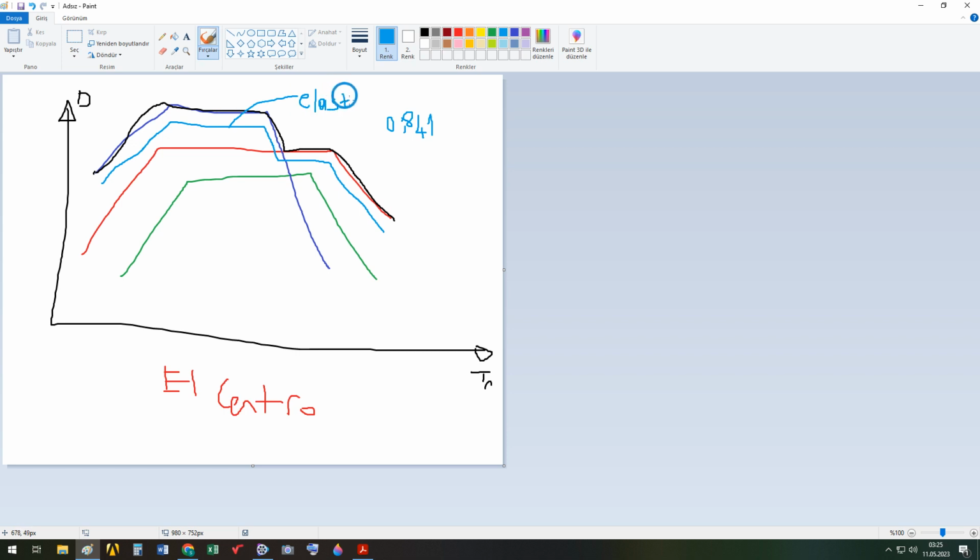Not very expensive. This is elastic design spectrum, which is created from the response spectrums of the earthquakes developed at the same place. Not 100% safe, but with 84.1% probability it is safe. But there is approximately 16% risk margin. Okay? That's elastic design spectrum.